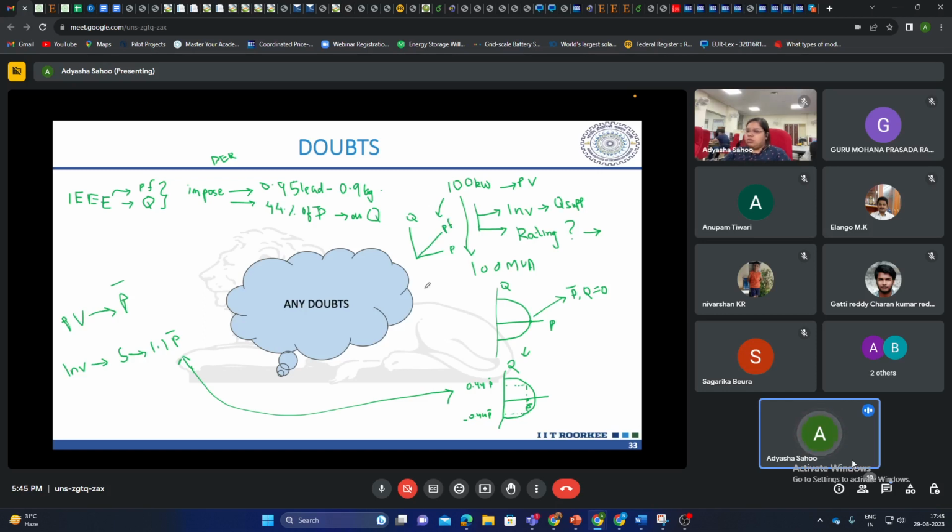So depending upon various modes of operation, you get this relation between PG and QG. Basically, PG is not controllable for most renewable plants. So according to this relation, whether it is in constant power factor mode or full circle mode, you can calculate the amount of reactive power. Such kind of variations you get.